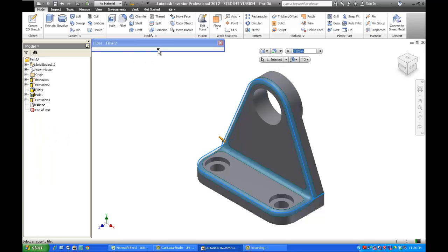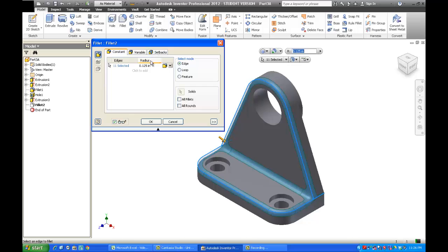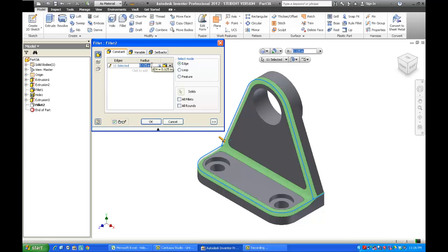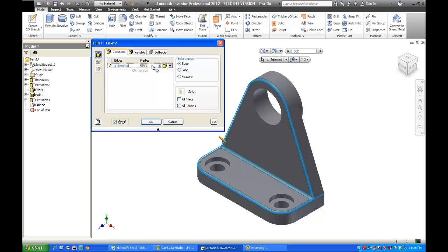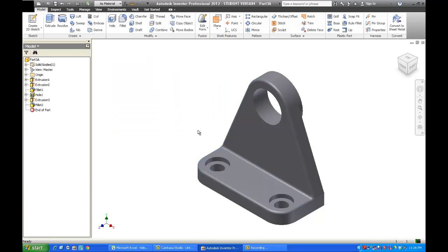Now it's going to pull up my fillet menu again just like before, so I'm just going to roll it out so you can see the whole thing. Now, I've got a 1/8 inch fillet on this whole thing. So let's say I want to do something different. Let's say we want to take that to 1/16 of an inch, so 0.0625. Look how it previews it. It'll do it. Boom. There. It applied it to the whole part. I edited the feature without having to redraw it all. Reselect everything. In my case, I still want it the way it was.